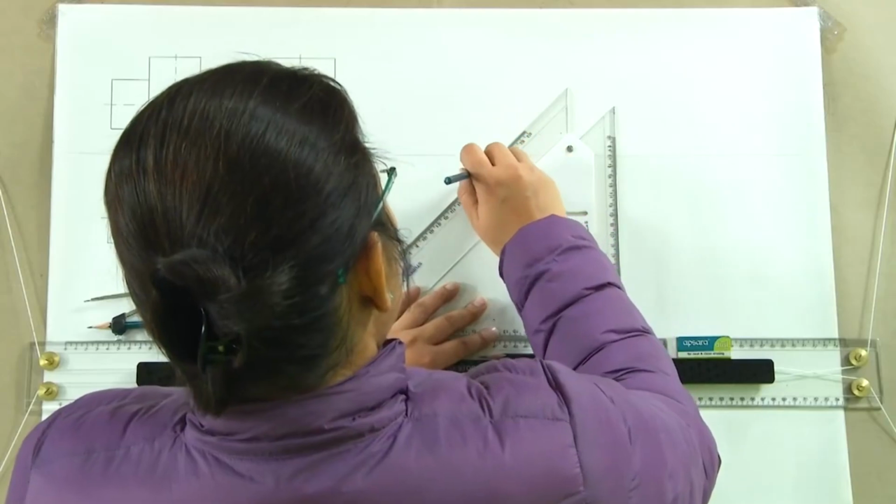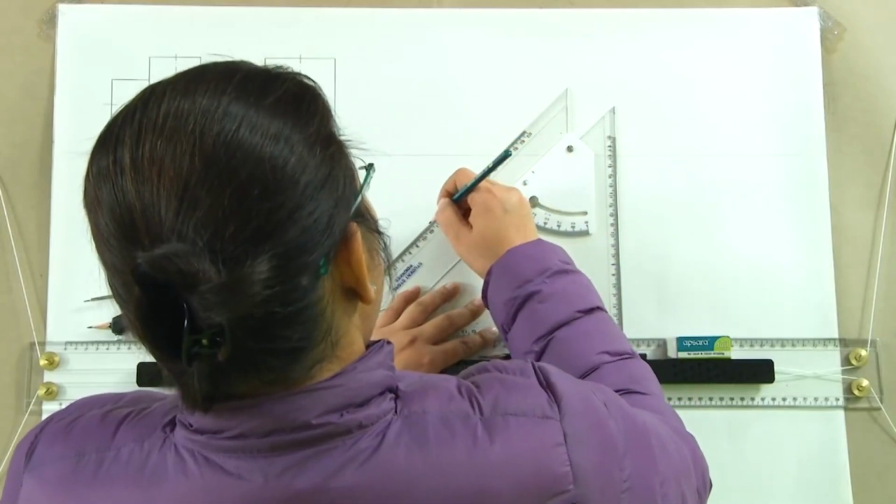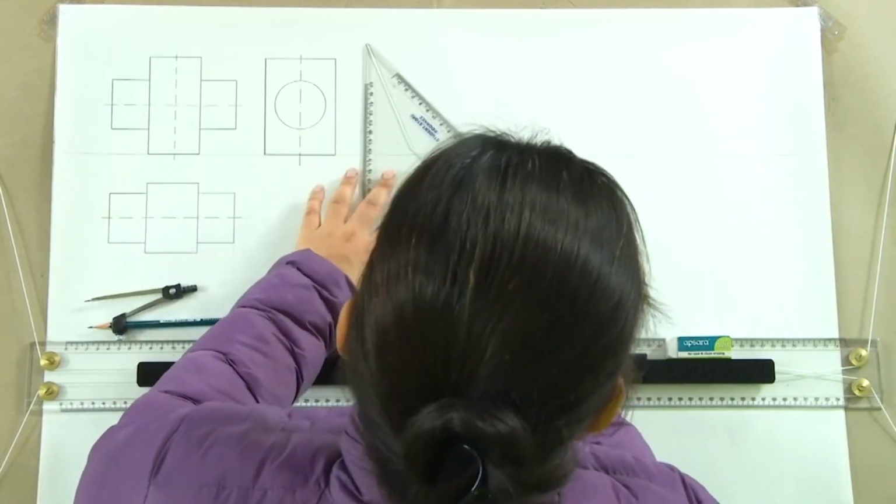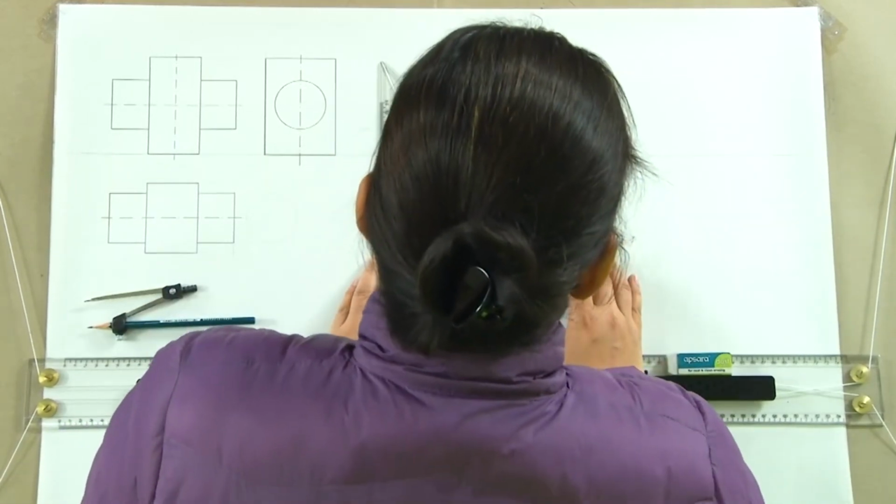So, we have to draw the projections of such a case, assuming only one solid at a time. So, what we will do, we will start with, say, the square prism. The square prism is assumed to be kept diagonally to the VP. So, the axis is perpendicular to HP, parallel to VP, and the base is put diagonally. So, we will make that first drawing first. Let us assume that it is a 10 centimeter square pyramid which is kept diagonally.